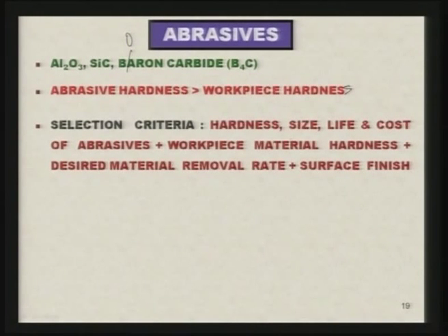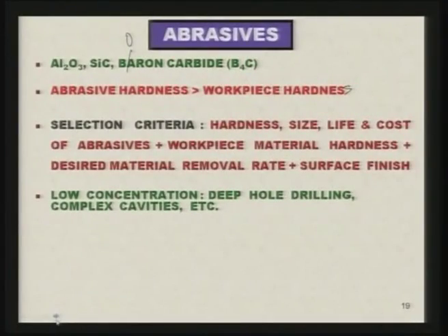Also, desired material removal rate and surface finish should be considered while selecting the abrasive particles. Low concentration of abrasive is recommended for deep hole drilling, so that the abrasives and the liquid carrying the abrasive can penetrate inside, specifically in case of complex cavities.